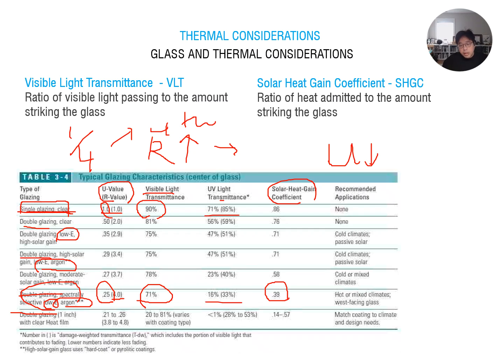So that's why it protects against UV light, protects against direct sunlight, and also protects against solar heat gain, so it means the double glazing system with the low E and the gas fill is much better, 4 times better performance compared to the single glazing system. So by understanding this kind of glazing performance, you can decide and propose for your cladding system. Okay.